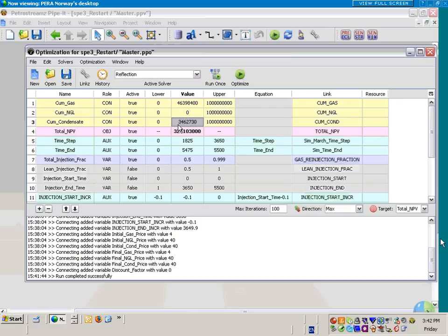So if the lean gas reservoir is more homogeneous, then it would probably, I don't know, that's why we do the optimization: where is the gas utilized most effectively? By injecting into the rich gas or the lean gas? Really this is the mechanism for trying to assess that. And how much gas and for how long. Those are the main things.